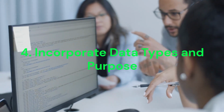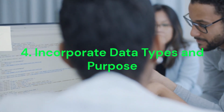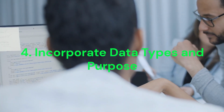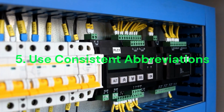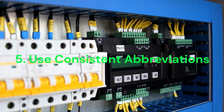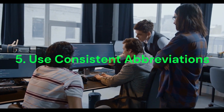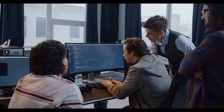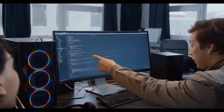Step 4. Incorporate data types and purpose. Use prefixes or suffixes like in, out, or stat to immediately indicate how a tag is being used. Step 5. Use consistent abbreviations. If you must abbreviate, document them and use them consistently throughout your project. Following these 5 steps will lead to more maintainable, readable, and professional PLC programs that save time during troubleshooting and make collaboration easier.